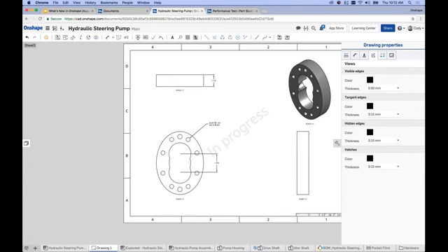So that is the views tab within the drawing properties panel. The key thing that you would do here is adjust line thickness within your drawing, and that's another very commonly asked question. Next to that is construction geometry. Like the name implies, this is where you'd set the color, the thickness, the style of center marks, and those kinds of details within this drawing.